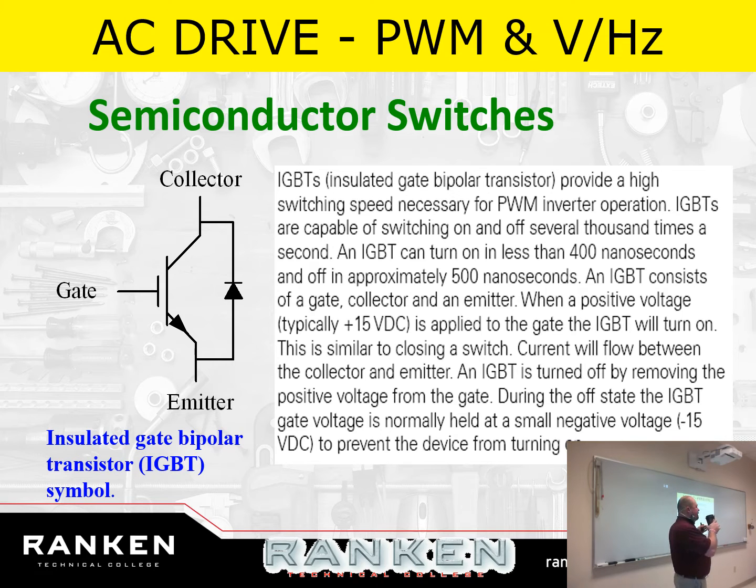So they're not the end-all be-all, but they did replace regular transistors or, call it, SCRs. Like SCRs, you can't switch on and off fast enough to make them fire that fast. So the IGBT fixed that, but the IGBT, because of its nature, caused a lot more problems. They can turn on and off in less than 400 nanoseconds. They can turn on and off literally 500,000 times in a second.